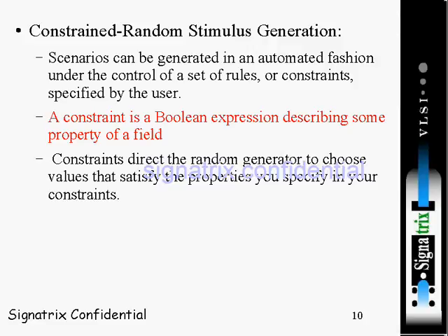In order to get the access over that bus, each master should raise a request signal to the arbiter. Based on that arbiter priority algorithm, arbiter will give grant signal to a master, right? So the master which gets that grant signal is going to access that bus. This is the basic functionality.